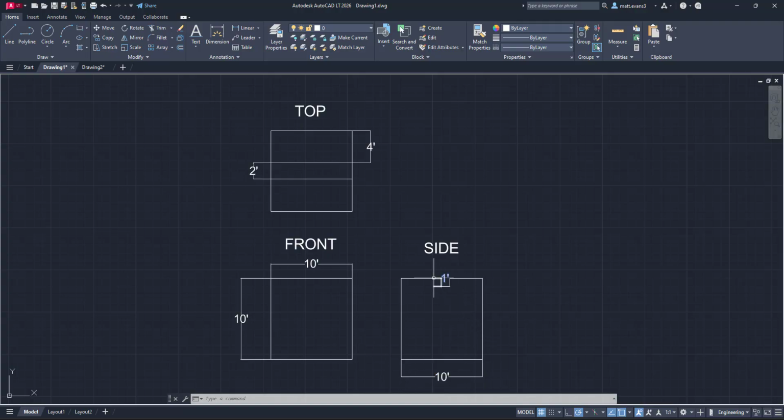And then you have a little divot cut out that looks like it's a foot inside the square. And if you come up here, you can see that that foot is 2 feet in length, and it looks like it's a channel that runs across the top of the square. This takes some practice and getting used to, to decipher what the shape is. But once you start getting the hang of it, you'll be able to do this pretty quickly. This is an easier object to follow, but it's a prime example of what a drawing would look like for you to make an isometric drawing for.